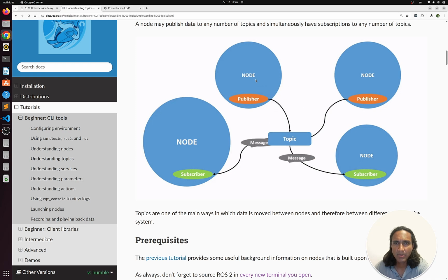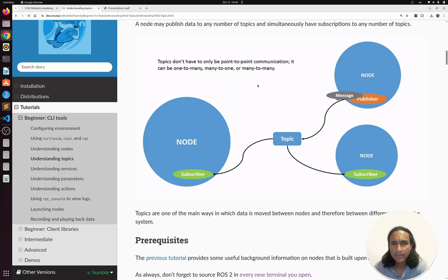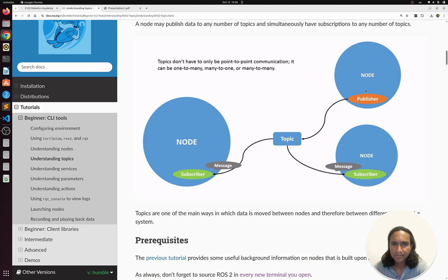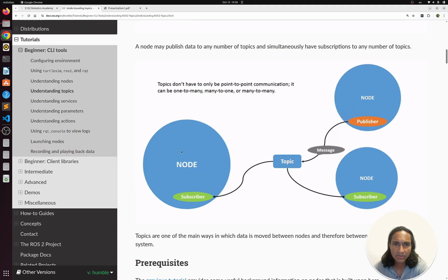One can publish information through the topic, and for instance, this could be the Python script we're going to be working on soon, publishing drive commands, and the subscriber can be the controller for the drive joints that listens to these commands and moves the robot. So again, this could be our Python script pushing data to the controllers, and the controllers subscribing and listening to that data.